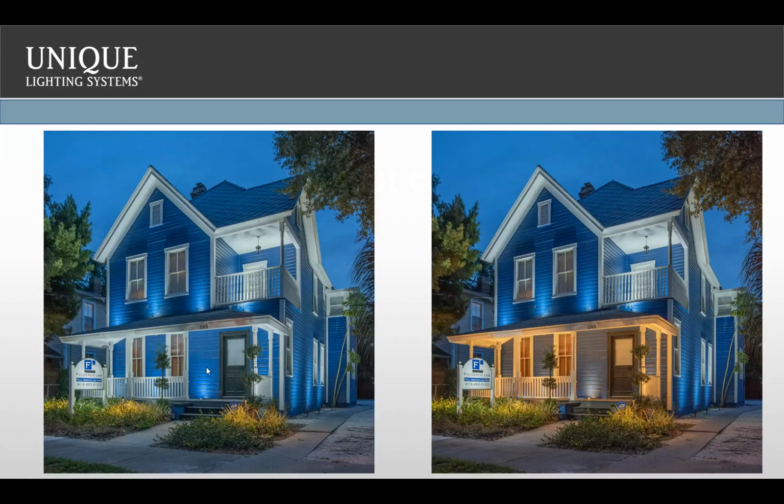One of the things I've been saying in my webinars lately is that here in Arizona we've got a lot of green cactus, and several guys I work with say, hey Brian, we're putting this green LED on this cactus, and boy doesn't it look great. To me, it makes it look cartoonish. It's almost like taking a green crayon and coloring over the top of an already green cactus. Versus a CCT of 3500 or 4000, which really brings the green out of the cactus instead of color splashing over the top of it.